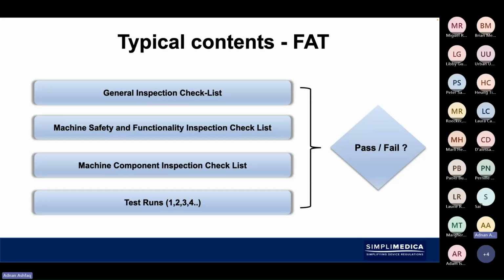You would know at that point what the acceptance criteria is. Depending on the piece of equipment, if it's customized and tailor-made to your requirements, of course it's not off the shelf, and that's where the user requirement becomes even more important, and that's where the checklist that you have will also become more detailed and granular at the factory acceptance point.